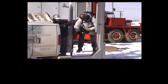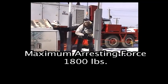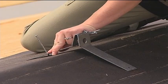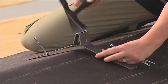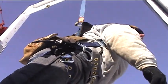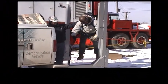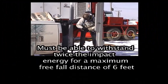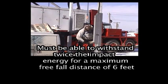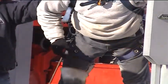PFAS must limit the maximum arresting force on an employee to 1,800 pounds. One must rig the PFAS so that an employee cannot free fall more than 6 feet nor contact any lower level. An employee must come to a complete stop and limit the deceleration distance to 3.5 feet. A PFAS must have sufficient strength to withstand twice the potential impact energy of an employee free falling a maximum distance of 6 feet, or the free fall distance permitted by the system, whichever is less.